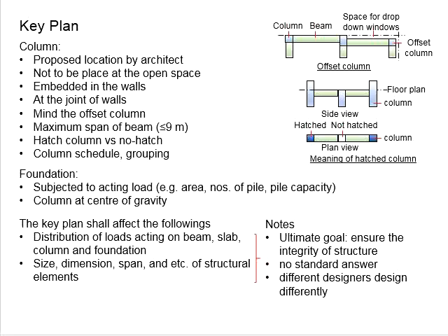This one requires proper design, which you are going to learn in geotechnical engineering. Especially for the local region, peat is one of the most common soils. Therefore, most likely it is going to be pile foundations. When you design pile foundations, in fact for all types of foundations, including footings, you need to be careful with the center of gravity of the columns. The center of gravity of the columns should be in line with the center of gravity of the foundations.